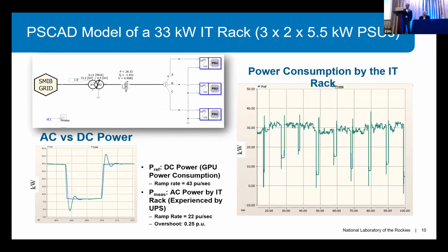So coming to the last part of my presentation, I want to talk about an IT rack model that we have been developing at the lab through a DOE-funded project that we are going to release in a couple of months. This EMT PSCAD model of IT rack. The reason we are focusing on this is, as I said, there are two main power electronic converters in data centers, UPS and PSUs or IT racks. UPS, we know how to model them because they are two-level voltage source converters, very similar to inverters. And that is the reason we are focusing on IT rack and PSUs. The model that we have, we can supply the GPU load profile and then see what is the power that the IT rack is consuming.